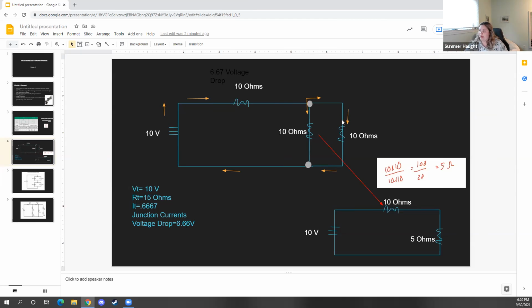We knew that the split happened and it has to add together. So these are the things that you're going to be asked to solve for, and these are the type of situations you're going to get. You're going to have to first calculate the parallel resistance, given the two different resistors you have in the combination circuit, then sum those together with the series part of the circuit to find different variables.